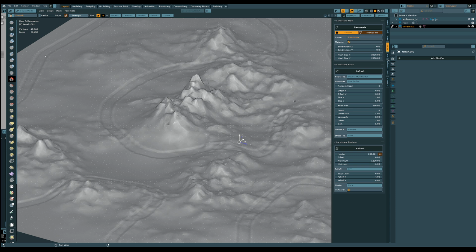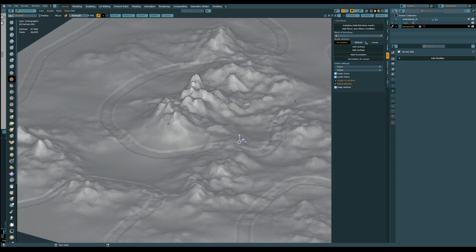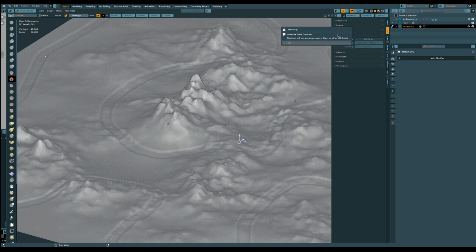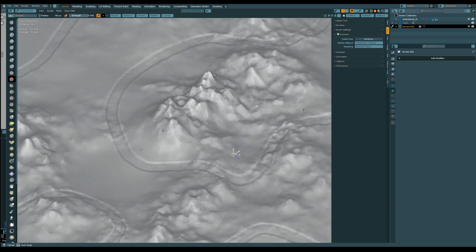But we go in first to edit. What is the tool? Is it in tools? So we need to expand dynamic topology and enable it, and from detail size change it from 12 to, let's say, 20. We don't want to overdo it.